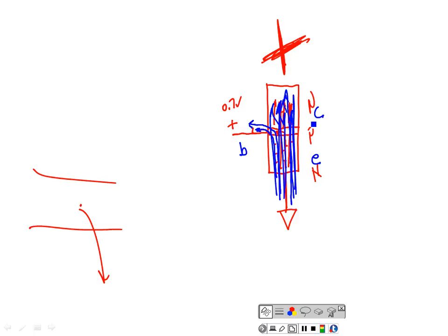So what we can do is control the size of the valve by controlling the amount of base current. But I don't get any base current at all until I get above about 0.7 of a volt, right? So if the base is less than 0.7 of a volt, the transistor is off. Well, we don't call it off. We call it cut off. The transistor's in cut off, right? Of course, the way it works is that I could eventually keep adding more and more base current, and eventually we would burn the transistor up.